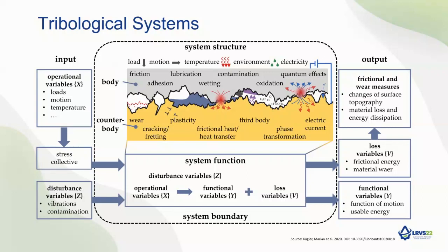The mechanisms and applications of tribology extend over several size scales. This ranges from processes on the nano or micro level in the field of physics, chemistry, and material science, such as the formation of boundary layers or shearing of nanoparticle layers, and ends up with machine elements and assemblies, as well as multiple tribological contacts in engineering sciences in the micrometer or the meter range, for example in rolling bearings or gears.